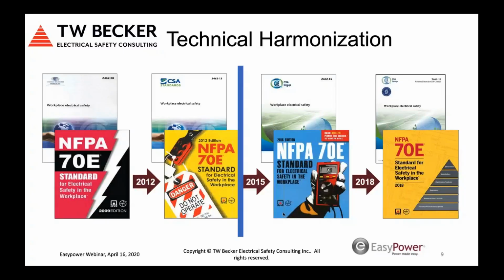they're what I call true risk assessment requirements. A general risk assessment procedure for a job, and underneath that, for individual work tasks, an arc flash and shock risk assessment. So harmonized, the big change again, and what I really applaud is the move to include risk assessment, which aligns with occupational health and safety management systems globally and risk assessment standards globally.